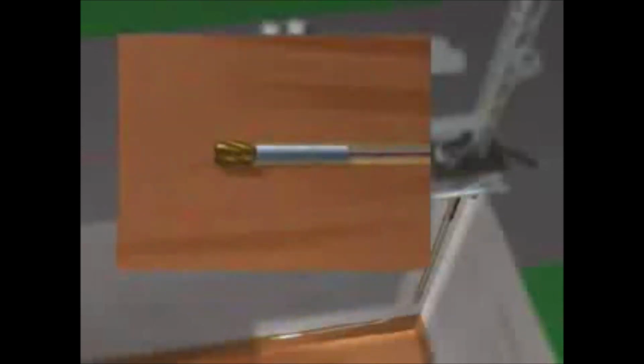The two-phase fluid exits the bit at the bottom of the hole, carrying drill cuttings up the annulus. Since the hole is drilled underbalanced, reservoir fluids such as oil or gas are produced from the reservoir and mingle with the two-phase fluid moving up the annulus. This means that the well is producing while being drilled.